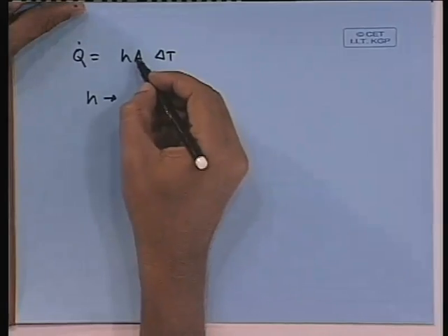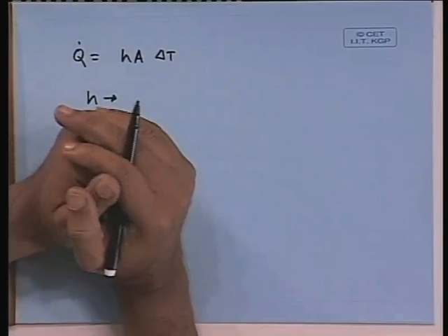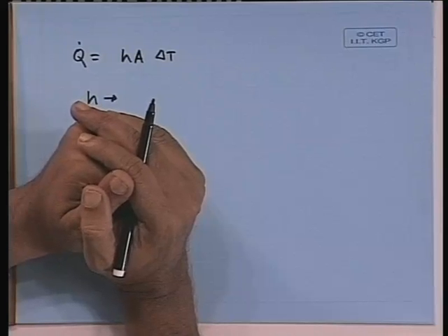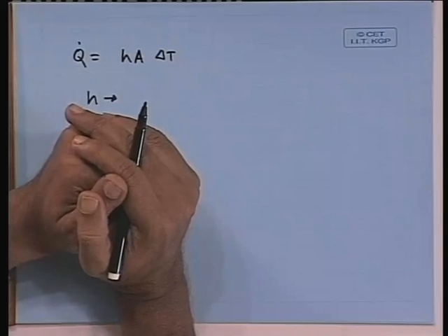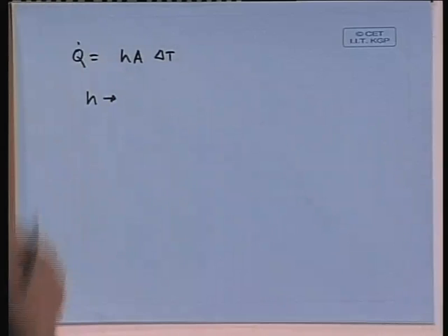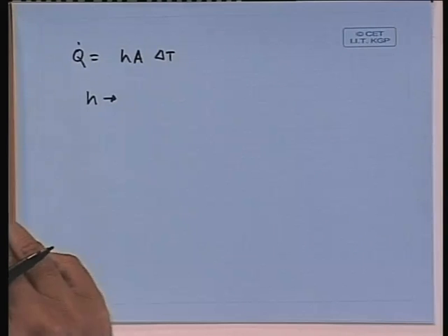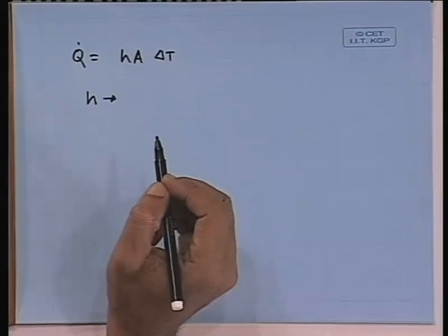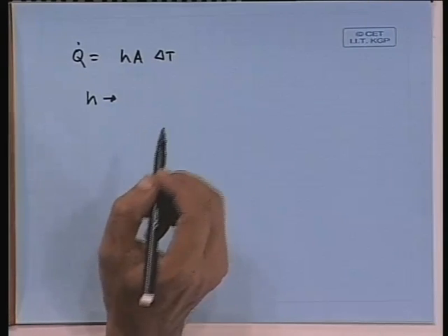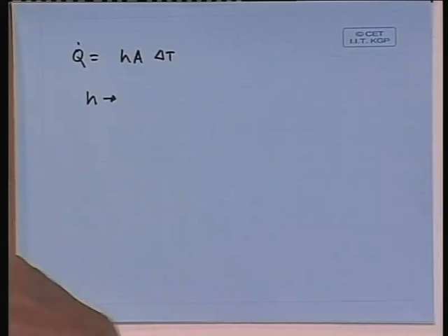H is equal to kilowatt per meter square per Kelvin. So, the coefficient will be dimensionless, no? No, the coefficient is not dimensionless. If you say coefficient of heat transfer, then it will be so many heat units per unit time per unit area. That is what we are telling, and then we are defining a non-dimensional number which relates this heat transfer coefficient, and that non-dimensional number is your Nusselt number. In the unit of H we are getting per meter square, rate of heat transfer per meter square.